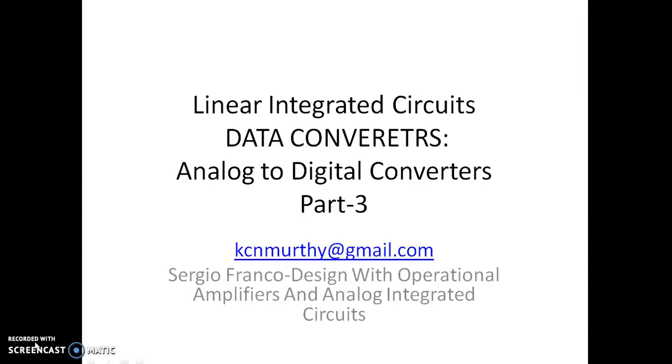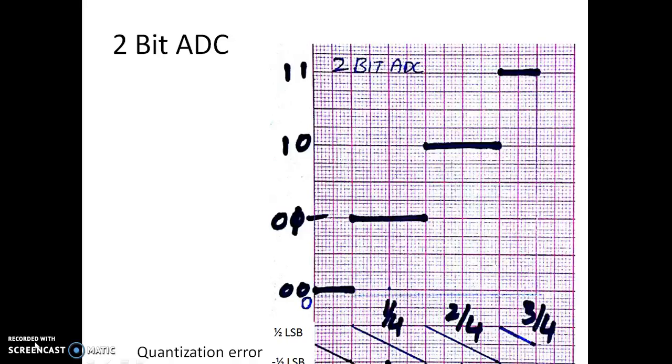Welcome to the third video on analog to digital converters. We shall consider the transfer characteristics of a 2-bit ADC. We know that a 2-bit ADC has 4 output combinations, that is 00, 01, 10 and 11. So we are plotting the input voltages of 4 different levels: 0, 1 by 4, 2 by 4, 3 by 4.